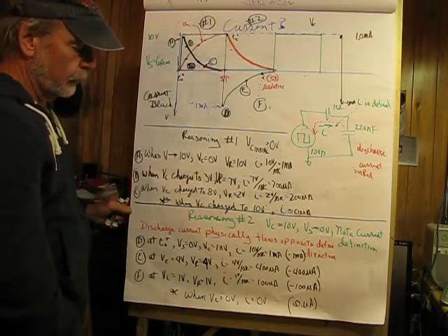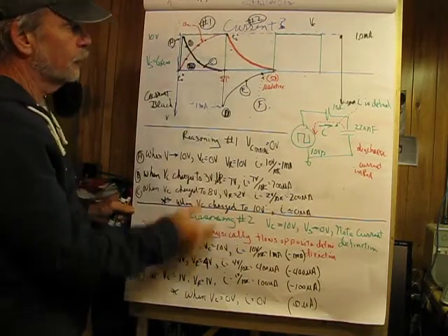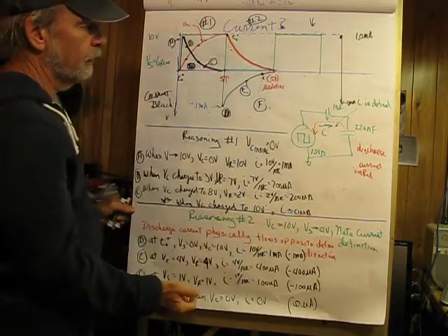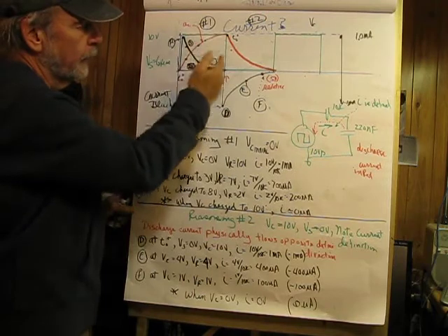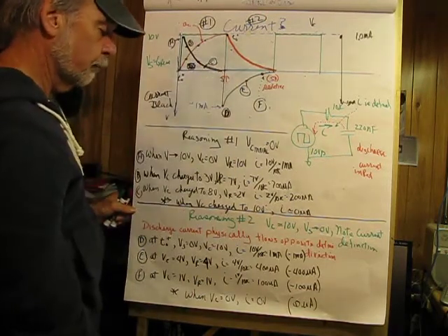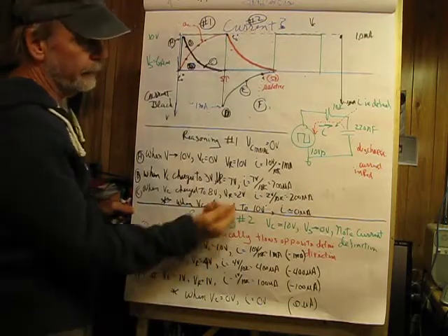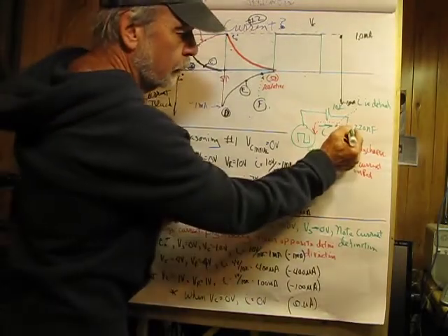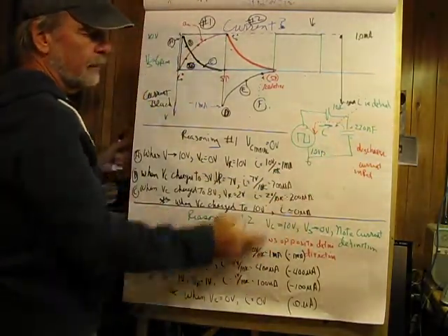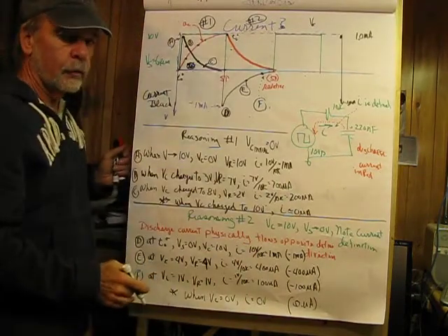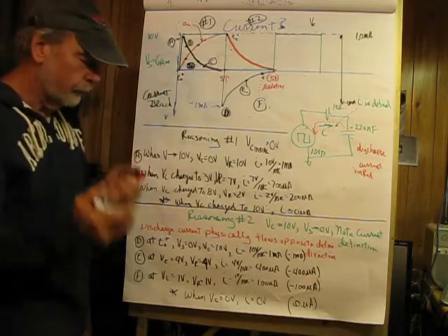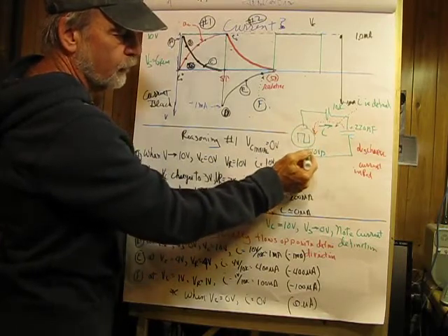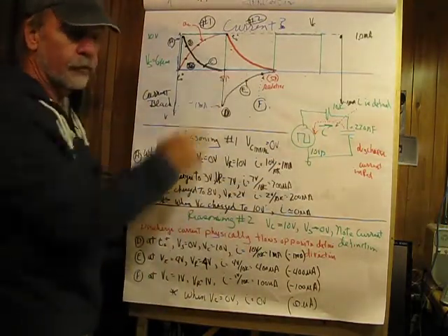Not too bad. Now let's look at the discharging here, and this would be number 2. That would be this guy. And in this case, VC is going to be equal to 10 volts. Why? Because it charged to 10. And the source now is dropped to 0 volts. So, the capacitor now sitting at 10 volts, and let me put polarity signs on this real quick, plus and minus, you have to realize that the internal impedance of the voltage source is 0 ohms. Very important concept. And the capacitor will now discharge through the resistor and across the 0 ohm source, which is at 0 volts.